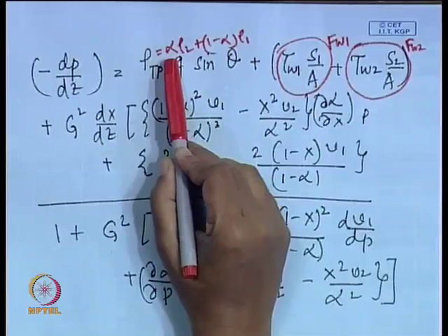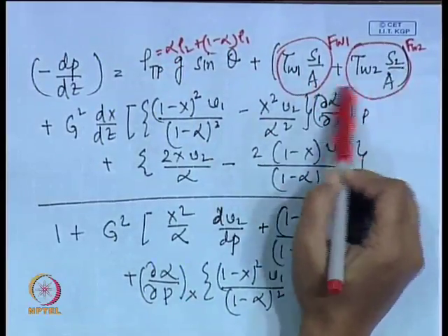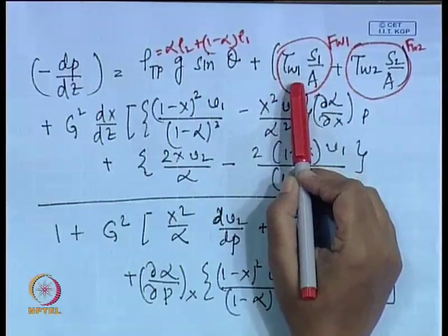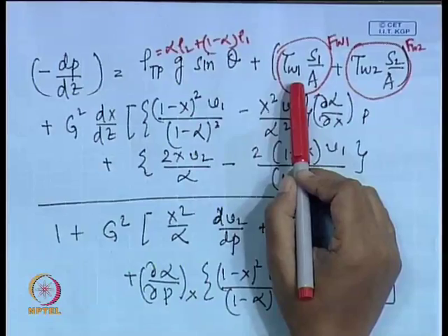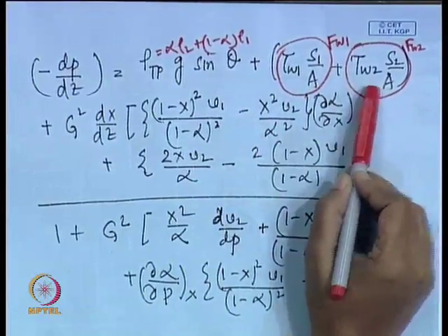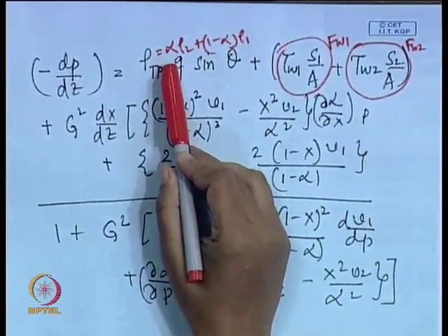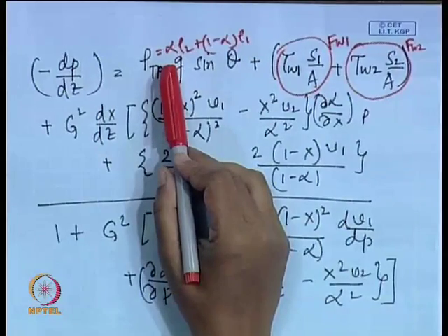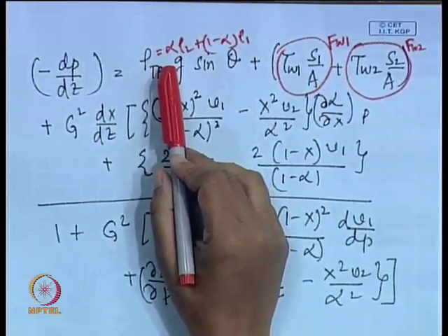So, for finding out alpha as well as the frictional component, a common technique is to use empirical correlations to predict the frictional pressure gradient as well as the void fraction. And of course, certain simplifications come up. For example, when only one component is in contact with the wall, which happens for annular flow, we have just Fw1, there is no Fw2.